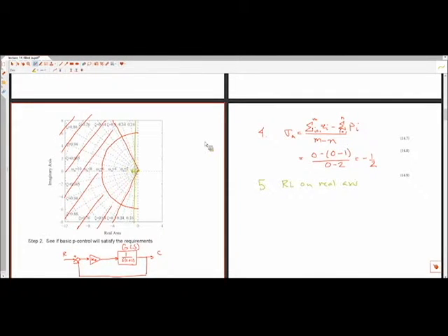It's not going to be proportional derivative. It's going to be something called lead controller. We're going to show how, all right, we said that this shape of this root locus is not sufficient to ever place the closed loop poles in this location. We're going to talk about how we can morph the shape of the root locus by tuning other gains in this.